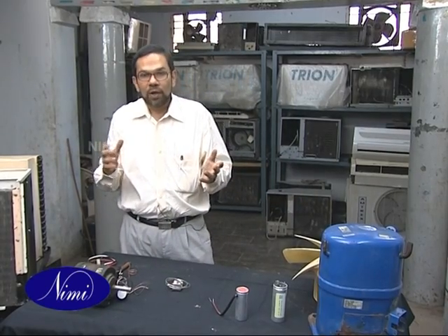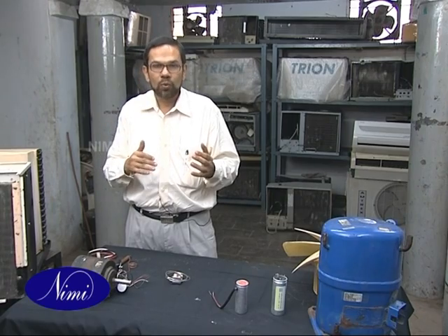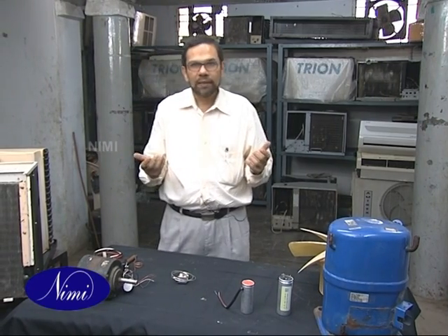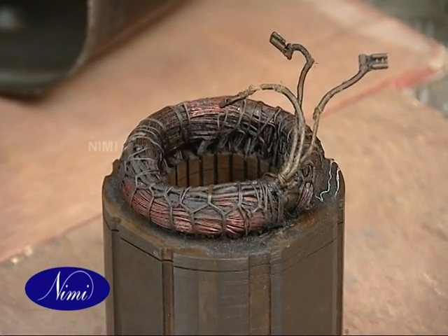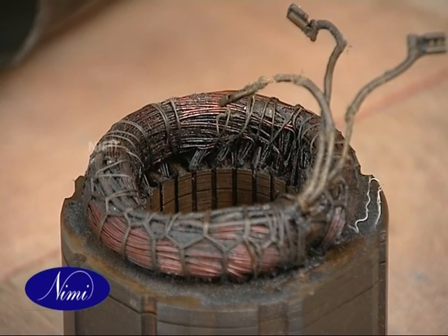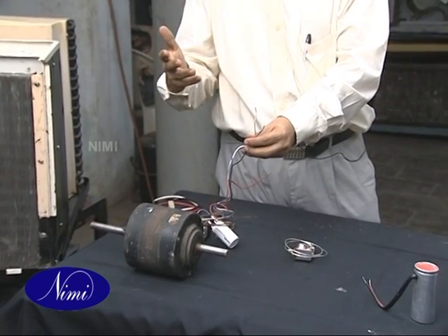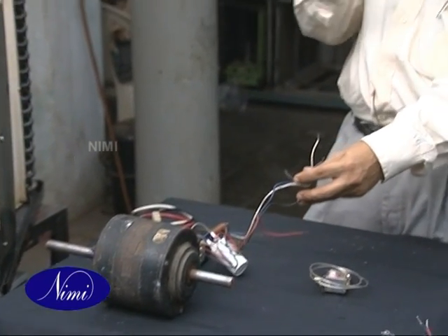Now we also have the operation of a high cool and a low cool. What is this, or how does this happen? We change the setting of the motor with a different winding to increase the speed of the motor, so we have a high cool. When we want less noise and less flow, we go into a low cool.